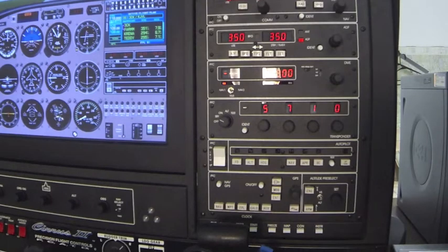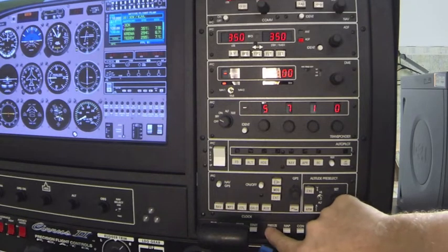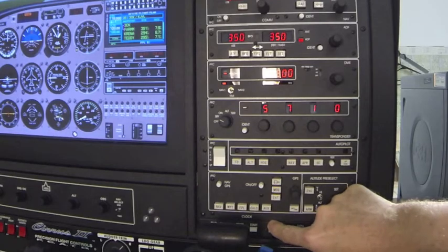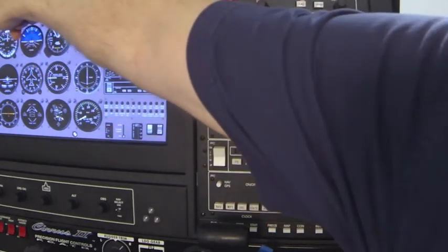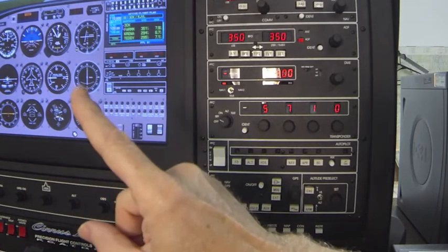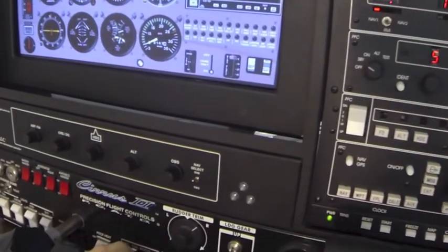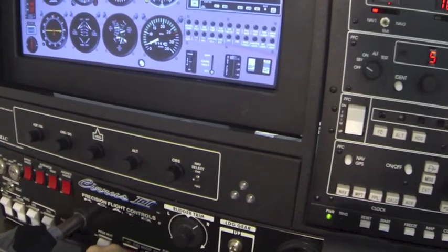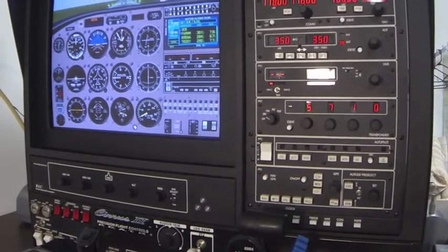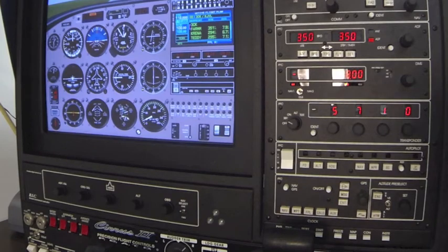Okay, with that done, I can now press over here the freeze button, which will take the airplane off of freeze. But the parking brake is initially set in the top left corner. It tells me that the parking brake is set. I'm going to take my finger underneath the yoke, way underneath the yoke on the left-hand side. Down here is the parking brake release button. Press it once, the parking brake has now been released. And so now we're ready to take off.